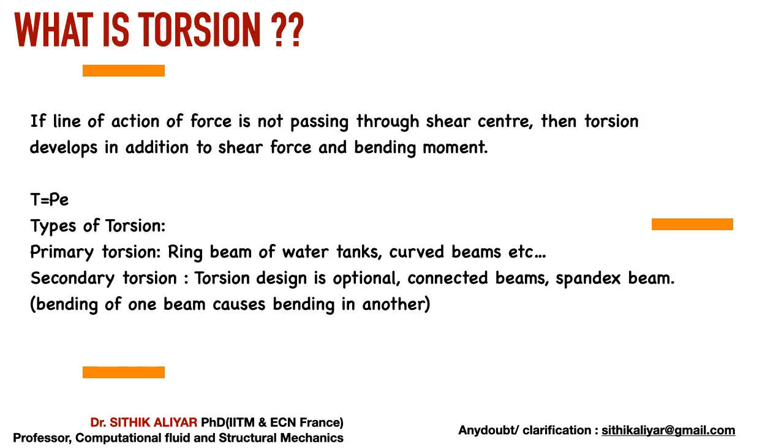If the line of action is not passing through your shear center, I hope you know what the shear center is. If you apply the load there, there won't be any twisting in the beam. Like a center of gravity or centroid, there is something called the shear center. If most of you don't know, please go through some online material to see what the shear center is. Every cross section will have a shear center point: C section, T section, rectangular section, everything. If I apply a load over the shear center, it will not create any twisting in the section. Twisting means, like twisting a chalk piece.